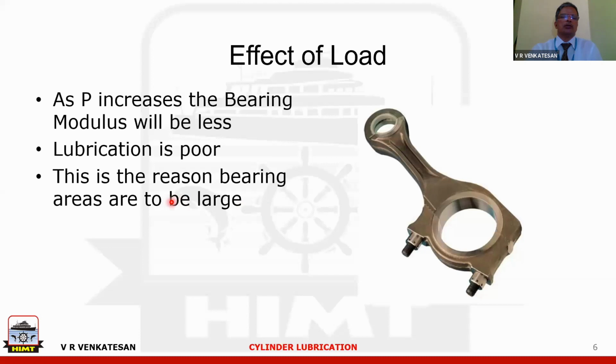So you can see this commonly known example, where in the connecting rod of a trunk piston engine, this cut is given at an angle. This is what we call an oblique cut like this. This oblique cut is given for the sake of making this whole diameter larger.